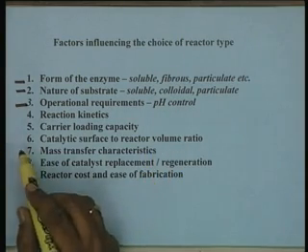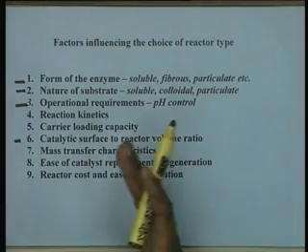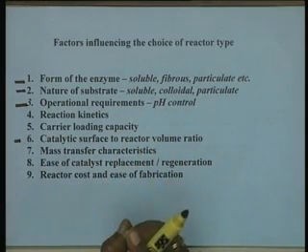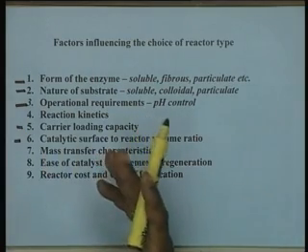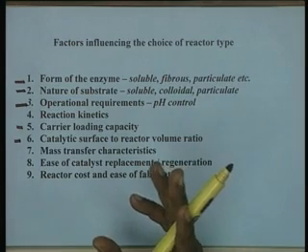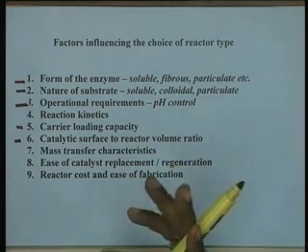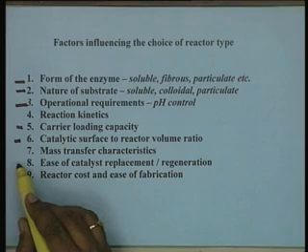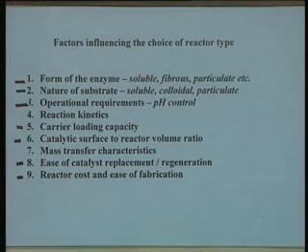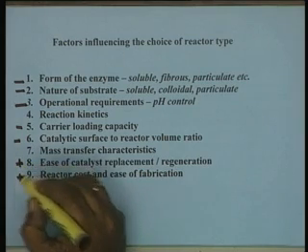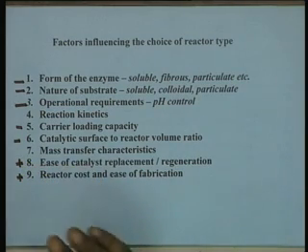Similarly, the catalytic surface to volume ratio is also fixed once an immobilized enzyme preparation is available. The carrier loading capacity also depends on the bulk density of the immobilized enzyme preparation and things like that. Then of course, ease of catalyst replacement and reactor cost and ease of fabrication are the factors which are dependent on the enzyme reactor, type of enzyme reactor.